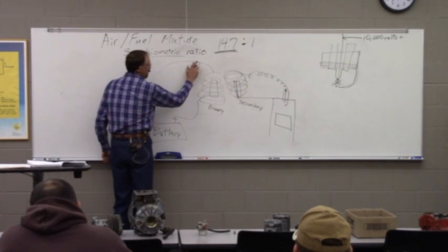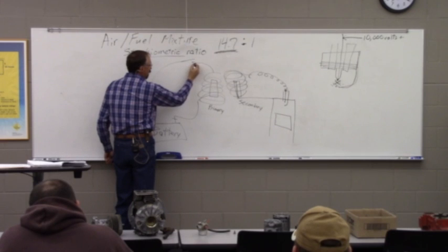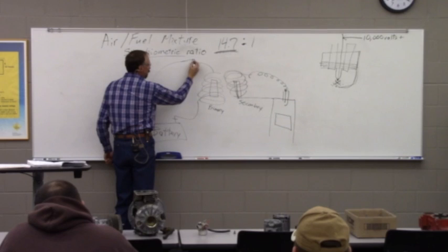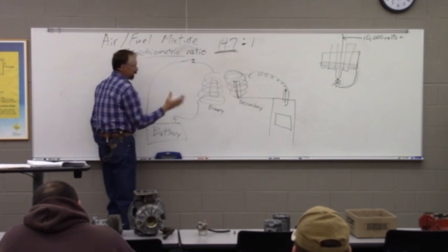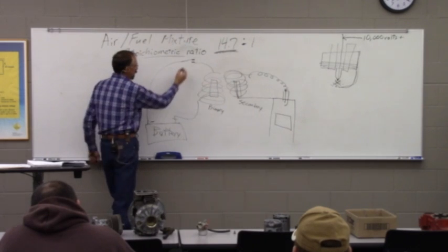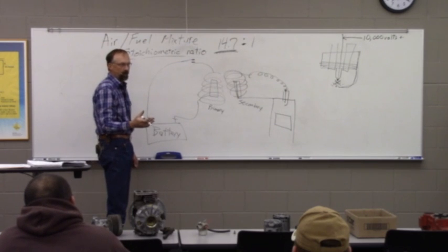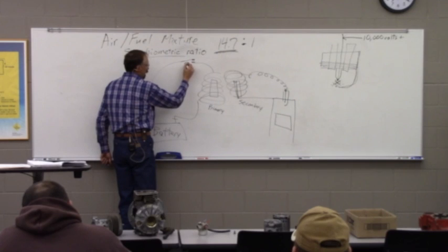Now, in our early vehicles, what we would do is have a set of mechanical contacts here. We'd have a little point there and a little point there. And inside what we call our distributor, we would have a cam, same as our camshafts that we were looking at the other night that run our valves, which is a round shaft, but it's got a bump on it on one side.